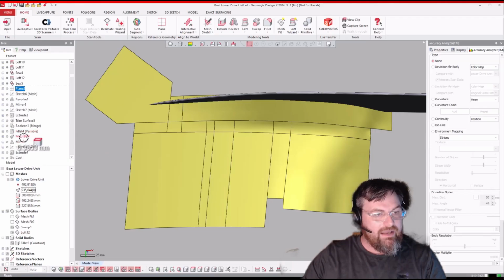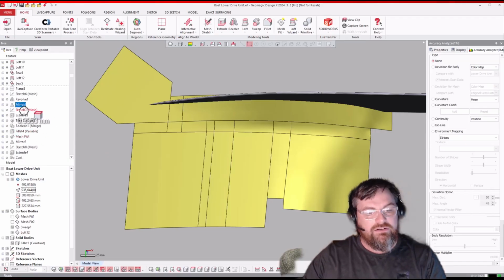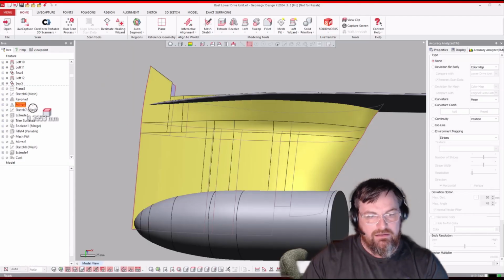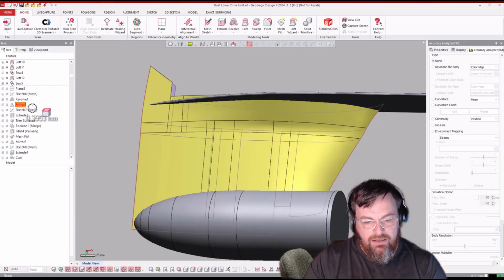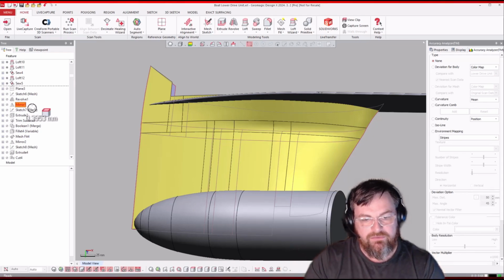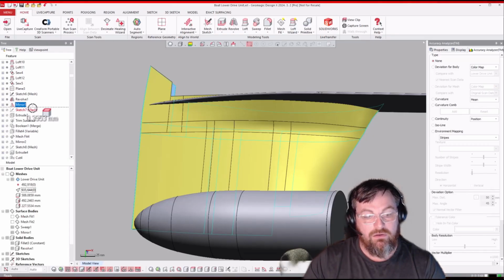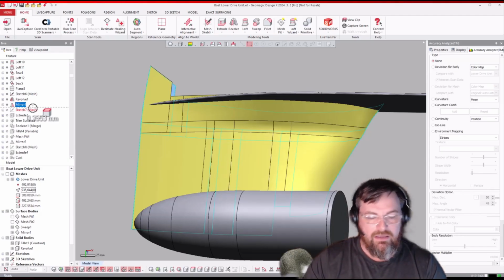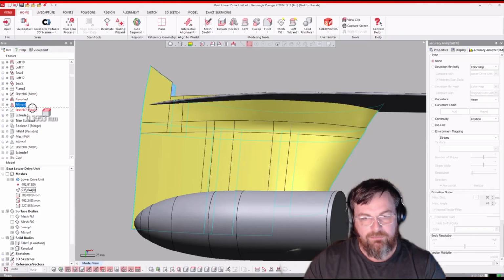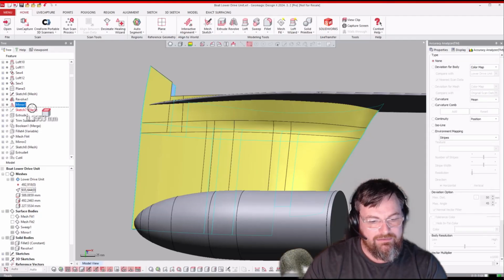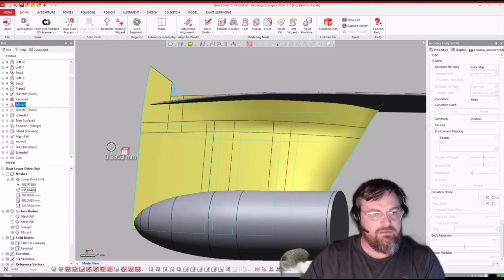So that is why you can cause wrinkles, and there are general modeling best practices in order to create nice clean NURB surfaces for CAD modeling. So there are some best practices that you learn in any software, whether it's SolidWorks, CATIA, NX, any of those. If you get into advanced surface modeling, there are these skills that you learn that are basically how to create nice clean surfaces so you're not creating wrinkly stuff here.